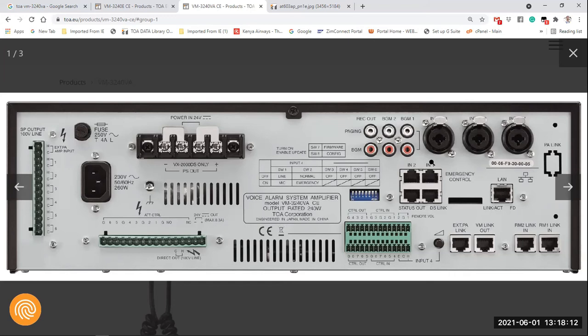Of interest for tomorrow, where we are programming now, we have got 6 emergency controls, okay? Let's take a Cat5 patch cable and we cut one side off, we strip our cables and we plug the other end in here. Right, let's take it. The first 2 colors will be the orange and orange-white pair. That will represent control number 1. So let me do this. I'll write here CTL1 on the form, representing control trigger number 1.